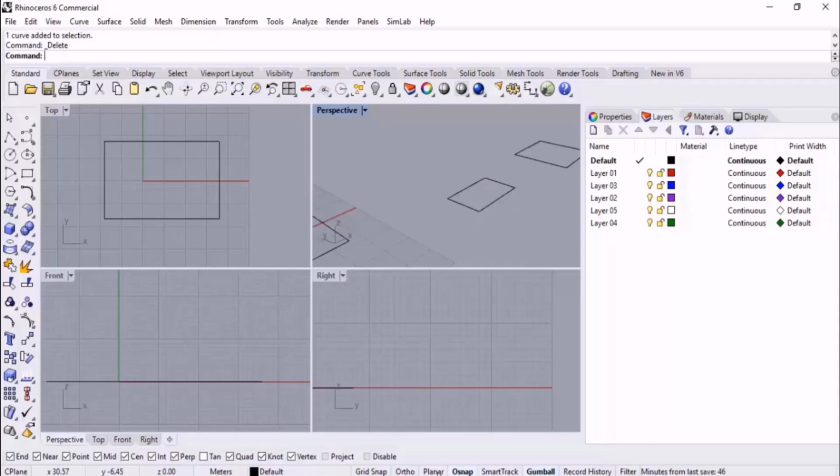I mean, it doesn't let the points switch the planes when you modify the views. So you can have all of your drawings in a similar C-plane. In other words, it keeps all of your sketchings or drawings parallel to the current work plane, and the main work plane or C-plane is specified by your first click. Let me give you an example here.